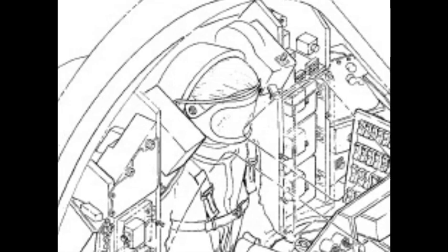The aluminum ring mates with the capsule forebody fiberglass attach ring during capsule to adapter installation. The top of the aluminum ring is slotted at 120-degree intervals to provide adequate clearance for the capsule retrograde rocket assembly attach straps when the capsule is attached to the adapter. A metal striker bracket is riveted internally every 120 degrees to the adapter skin. When the capsule is attached to the adapter, these striker brackets depress, open, the capsule adapter separation sensing switches located on the bottom of the retrograde rocket assembly attach straps.